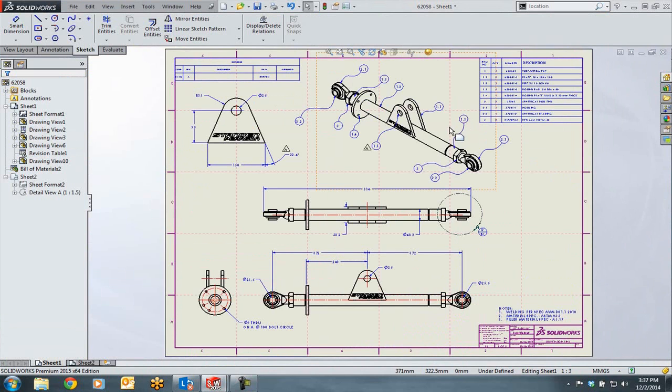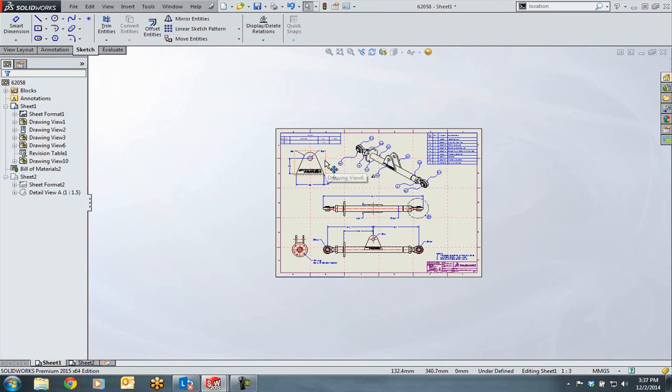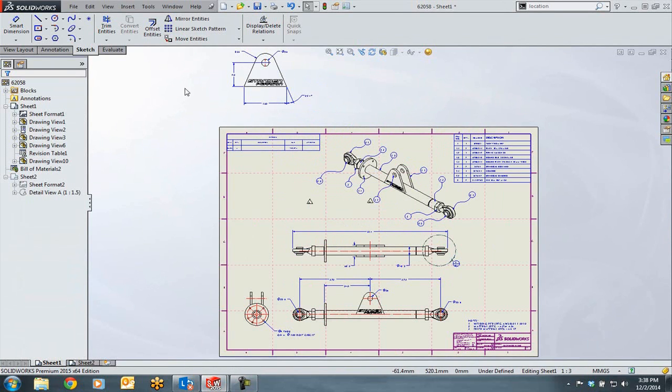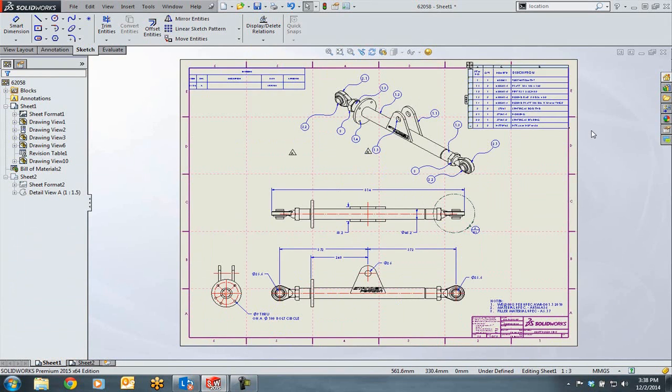Lastly, it is common to have to move a drawing view off the sheet to get all the information you want in a drawing. However, once this is done, Zoom to Fit will zoom to include everything located in the drawing file. Customers would commonly make a custom view that just included the actual sheet. Well, in 2015, SolidWorks has made this a standard view option. You can choose Zoom to Sheet from the View Palette toolbar. That's what's new in Drawings in SolidWorks 2015.